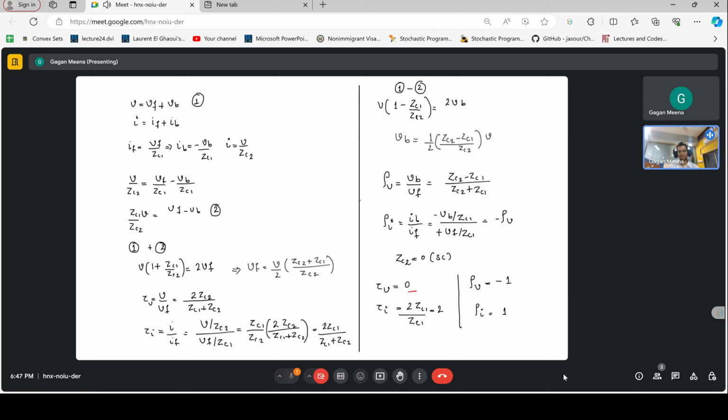So this is the next question. It is a continuation of that only. But here now we have one transmission line having surge impedance of 225 ohms. So this is ZC, and it bifurcates into two branches of surge impedance, 100 ohm and another 150 ohms.